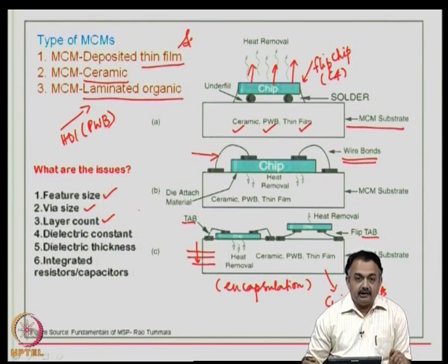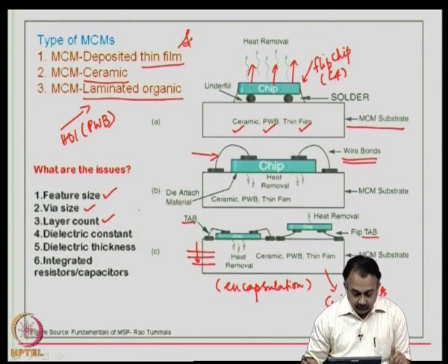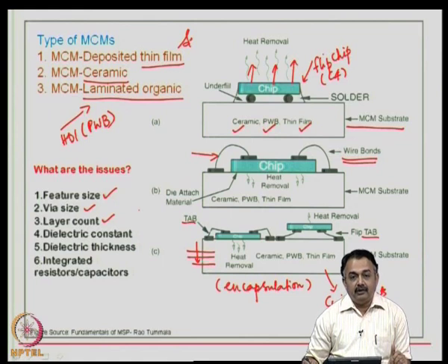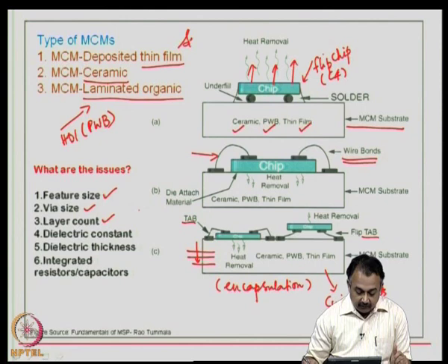Now, optimization in this case is very important. Layer count depends on the pad density or the pin density of the total number of components that are employed in this multi-chip module, and the kind of fan out that is required from the die to the substrate, because you have to take care of the power delivery, the ground pads, the ground layers and signals to be effective in electrical performance.